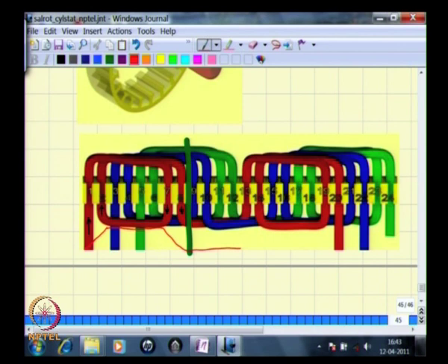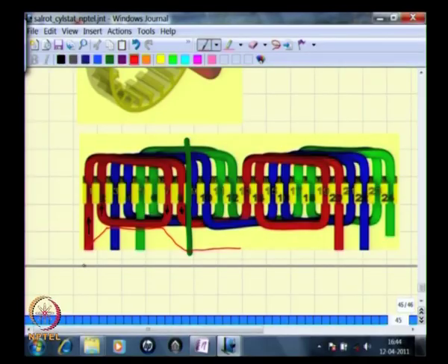So now you have the trapezoidal nature of the MMF which we have seen when we considered the distributed winding self inductance. It is the same thing that happens here, and if you plot the fundamental component of this, that would reach a peak right at the middle, and therefore the axis of the R phase winding is considered to be along the place where the maximum of the fundamental component occurs, and that is at this point.